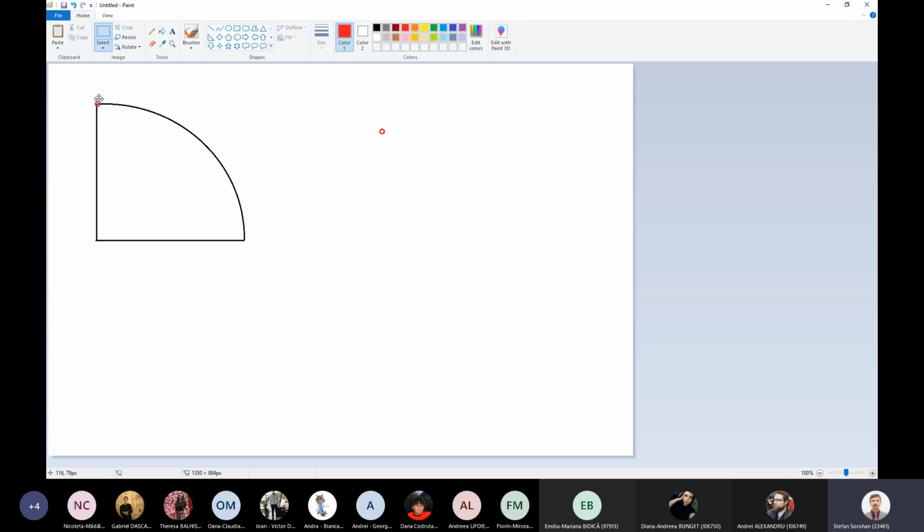So I need here a node. I need here a node. Also here a node. And after that, let's increase the number of nodes. Let's put one at 45 and 2 nodes between, that means 22.5 and 45 plus 22. Okay, and we can, for example, use this kind of mesh.